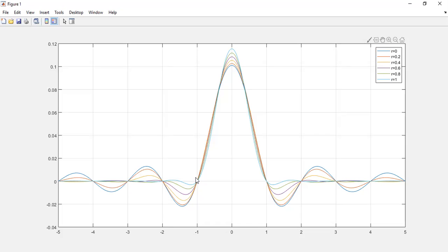It is practically a time limited signal because even in infinite time, it is not going to have enough energy, it is not going to have enough amplitude to really affect my recovery or my decision making process in any way. And the idea is that essentially I have a very good disposition already. So there is really no need for consideration of such timelines that exist from minus infinity to infinity, right? Hence, the raised cosine system is very effective in that sense.